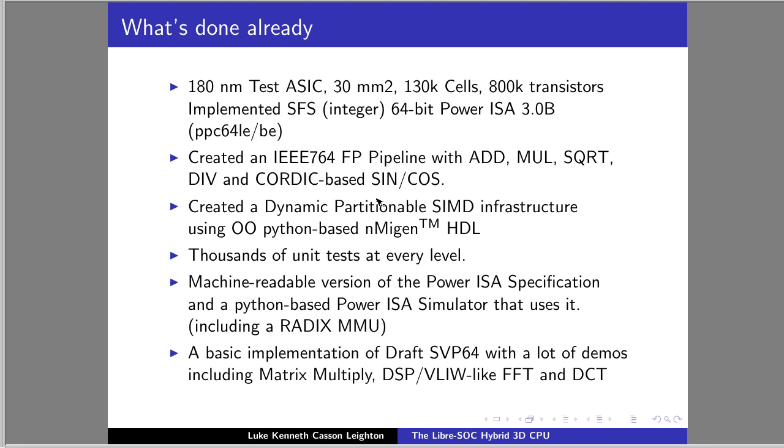We ended up with any instructions that used pretty much those registers, and likewise we ended up with an ALU pipeline and a logical pipeline and a multiply pipeline. So basically we planned ahead for a superscalar architecture, but then threw it together behind a finite state machine with an instruction per clock of about 0.1, very similar to Pico RV32. And this is just purely practical reasons of time.